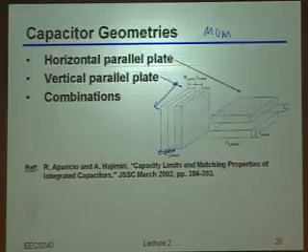The spacing I could also, in principle, control. Now you said the only thing you can control is the length, and I actually kind of agree with you. Why did you say that? DRC rules. Okay, specifically what about the DRC rules? You can only have the metal lines so close together and so narrow. Now, why do you want them to be very close together and very narrow? Higher cap and higher density. Yeah, right, the closer I make them to each other, that's the distance between the two plates, right? The smaller I make that, the higher cap I get.